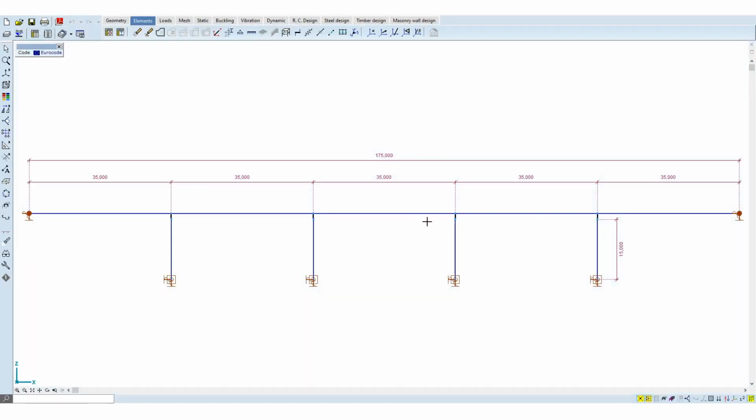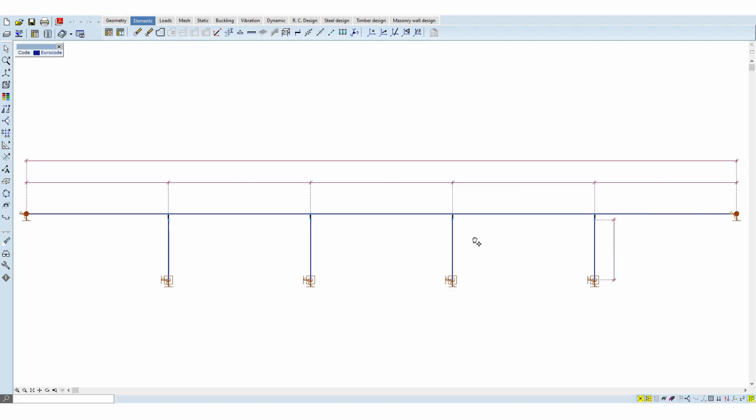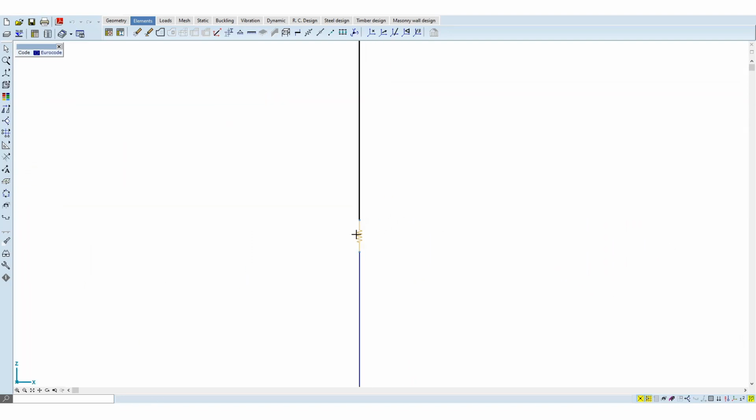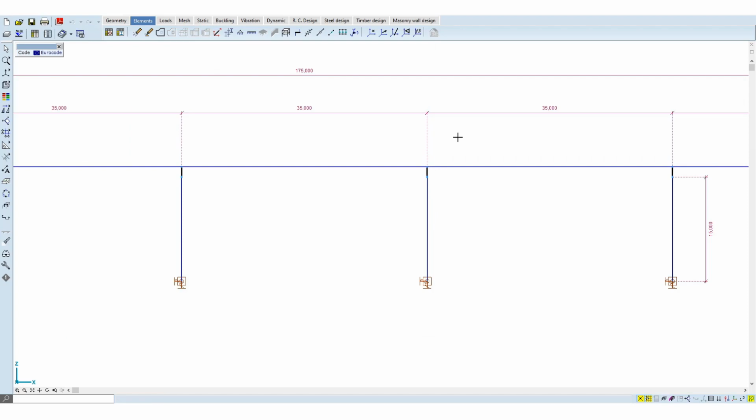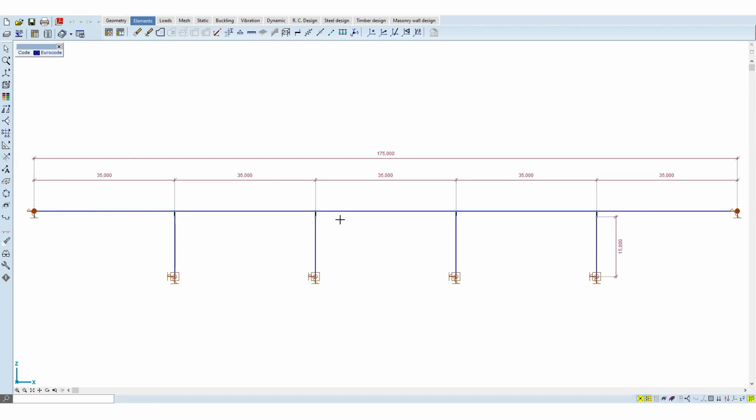Rigid supports are assumed at the pier feet, while the abutments provide only vertical and transversal support. The deck is connected to the pier through spring elements, modeling the bearings of the bridge, and rigid elements are used to account for the eccentricity of the deck. The deck is fixed in the longitudinal direction only at the third pier to provide free movements of the bridge during thermal expansion or contraction. This means, however, that only one pier has to take all the longitudinal forces caused by an earthquake.